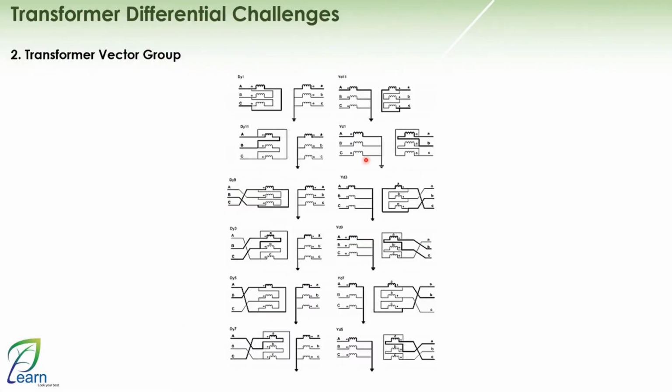This is, of course, the problem we refer to as zero-sequence current elimination. And of course, we have different vector group connections, such as Dyn1 or Dyn11 and so on. There are many connections, and as we can see in the diagram in front of us, it shows, for example, Dyn1, configured in this way. When you draw current from phase A on the other side, where will you draw from? From the cables or from outside your circuit?